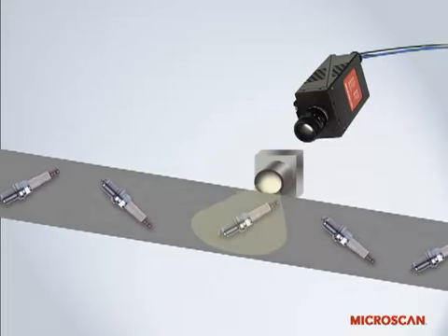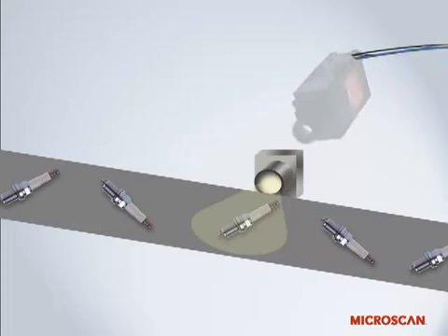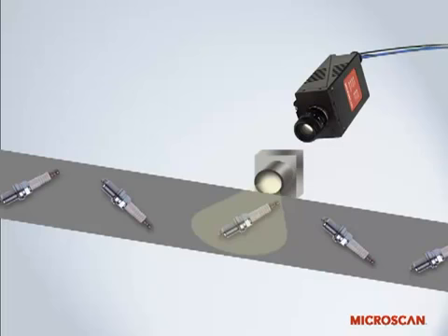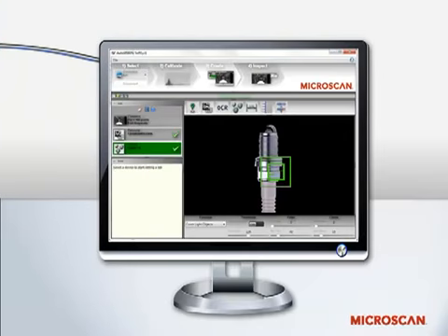First, you have a manufacturing production line with a steady flow of objects. Then you have a camera or optical system trained on the line. Next, you make sure that you have proper lighting of the line so the camera can see the necessary details. The camera captures digital photographs and analyzes the images against a defined set of criteria.